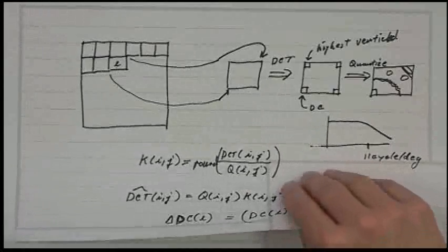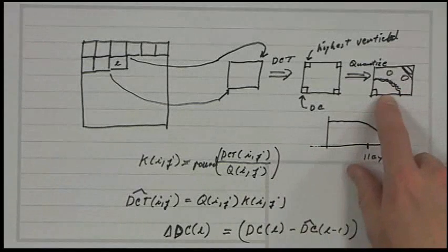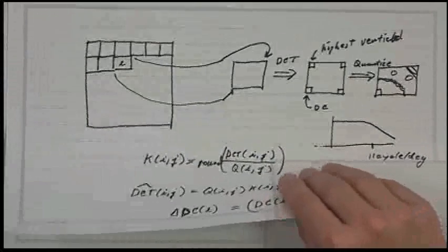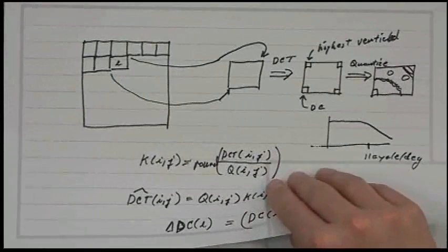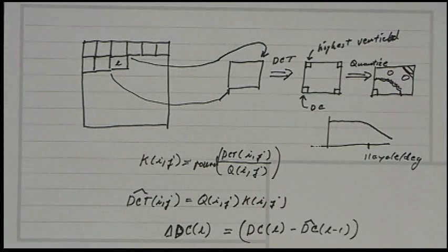So the high frequencies are important, though not as important, and you wouldn't want to just get rid of them all. The logical conclusion of that would be to transmit one pixel for the whole image: just average all the pixels and send one value, right? That's like the lowest frequency. But obviously you need more information than that. So the trick is that it's really a rate distortion problem. For a particular rate, you want to get minimum distortion, or for a particular distortion, you want to minimize the rate.